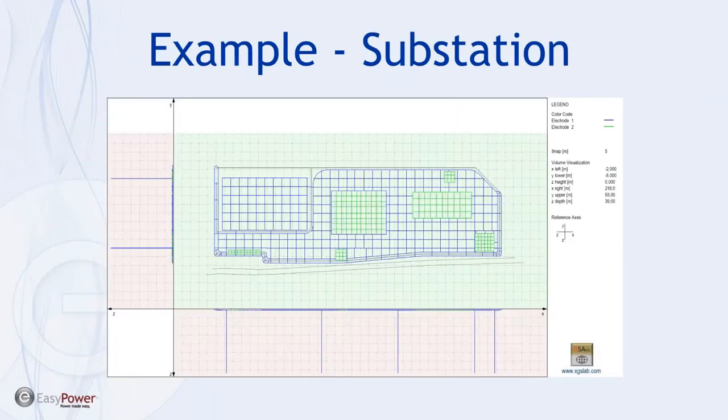So jumping right into examples now, we can see an example substation grid layout. This is just showing the below grade conductors for a substation. We're not modeling anything above grade at the moment. The blue is the grid, so consider that maybe 4/0 copper or something like that. And the green are the foundations. You can see that the foundations in this case are bonded to the grid in certain locations.